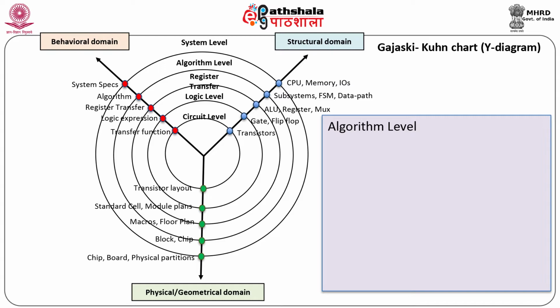The behavioral description at this level utilizes general expressions to specify data transfer and uses an extended finite state machine, that is FSM, to describe the system design using register transfer mechanism. All register transfers use a common clock signal.